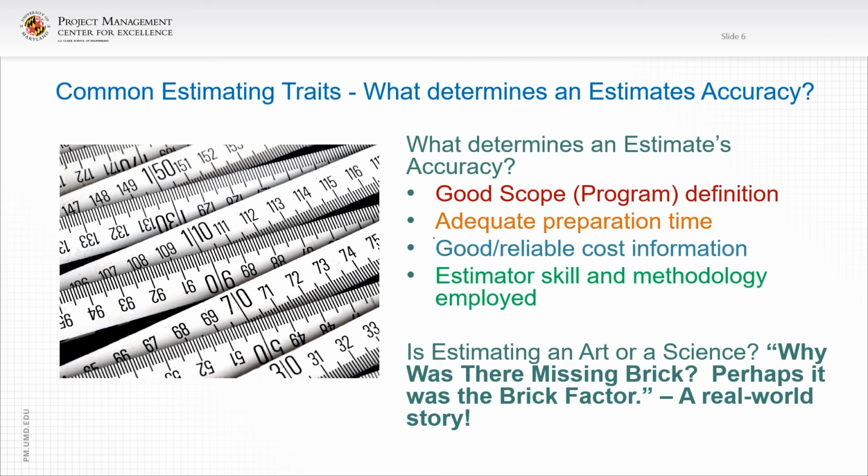So you need to be real careful how you do a brick factor and how you calculate the brick factor, because when you multiply it by the surface area of a building, it can really create a discrepancy. So that was a real world story of how the job thought 25,000 brick were missing, stolen, or just disappeared. But it actually turned out to be the brick factor error.